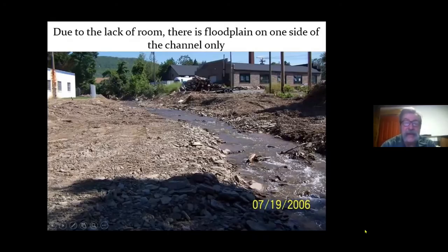So, here's an example. We've got some structures in here, so we can't get that maximum floodplain, but we can get it on one side or the other. So, you don't necessarily have to construct that channel right in the center of the floodplain. You construct it where you can. You want to get all those elements that Jeff talked about, that sinuosity and that slope, to match as close as you can to what should be there based on the valley that you're in. So again, get the floodplain where you can.